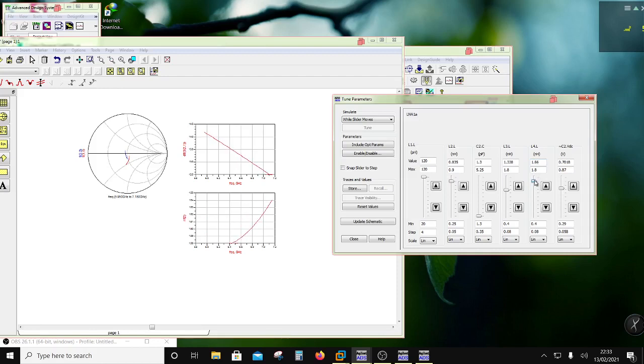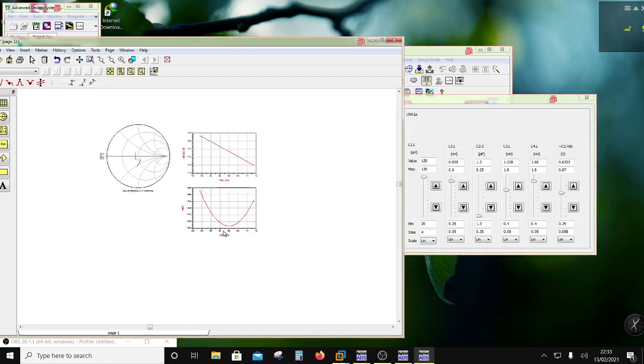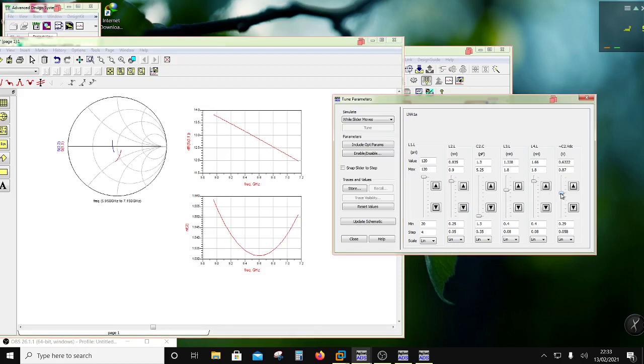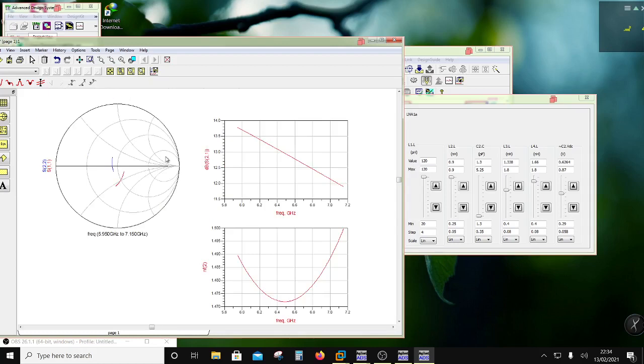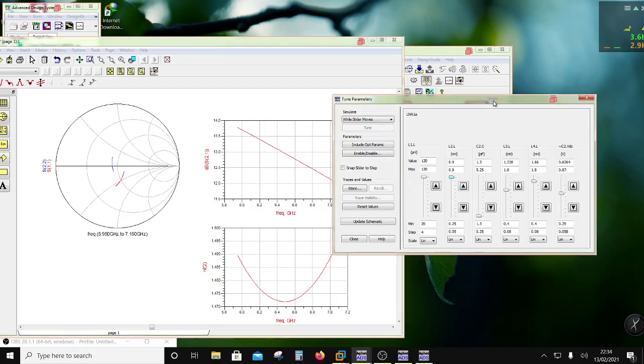So really this doesn't buy much, and the current is too high. So now we are at 5.5 something. Okay, keep an eye on the match also. So now we are at 1.4 something, but then you see S11 is kind of mismatched, right? So we have a series cap and a shunt inductor, right? So we are at a noise figure of less than 1.5, right?